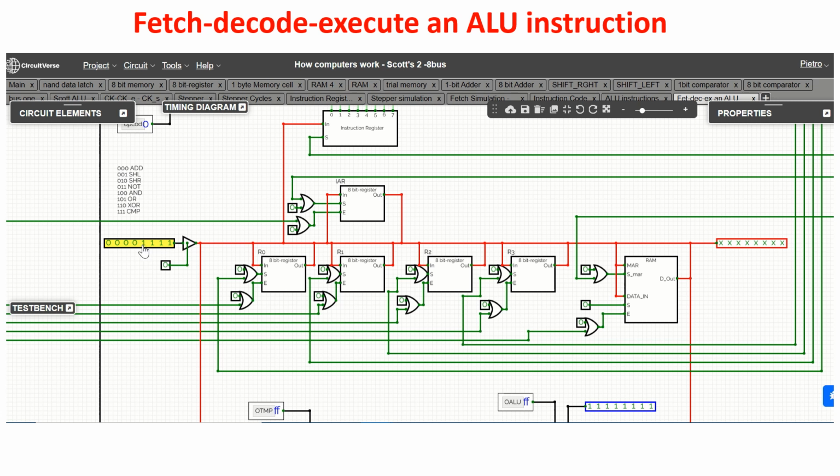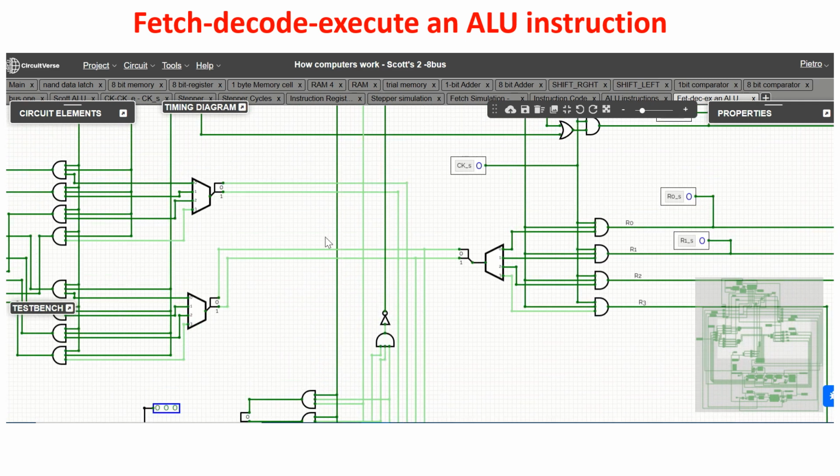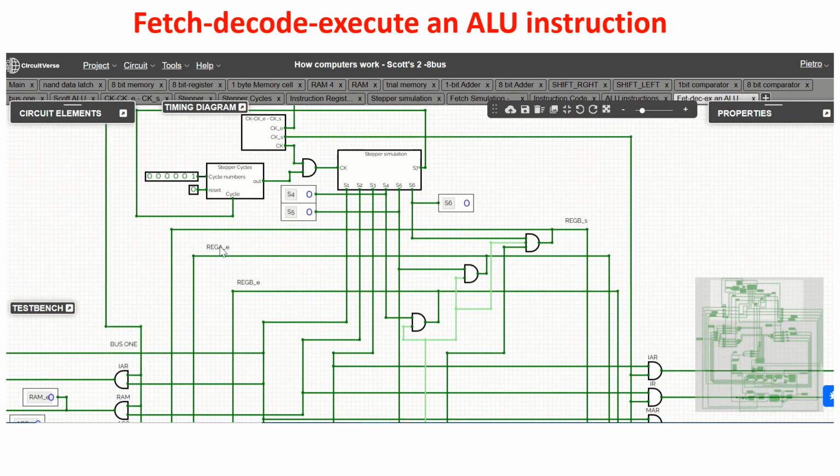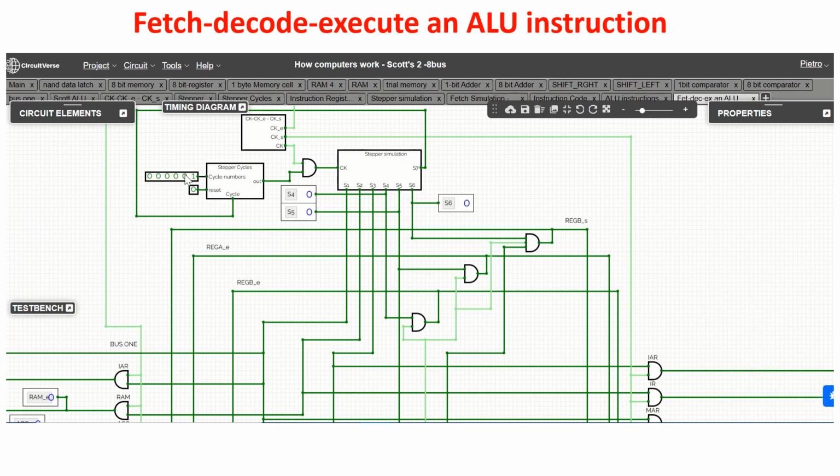So we are going to expect inside register 3 at the end of the operation 1 byte, all 0, but the 5th at 1. So I put this byte inside register 3. Okay, let's see, inside register 3 there is this, and inside register 0 there is this other byte. Okay, so let's go to run the simulation. Again, it's just one instruction, so I leave this at 1. I want just one cycle. I give an upset pulse and the cycle is performed.